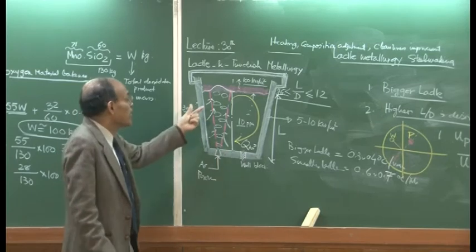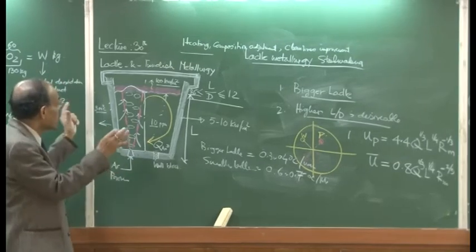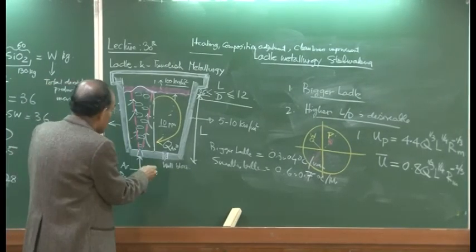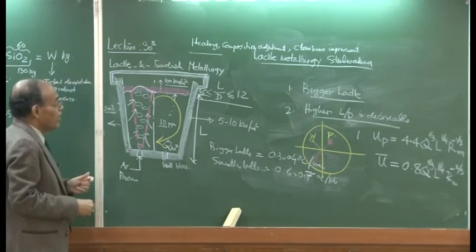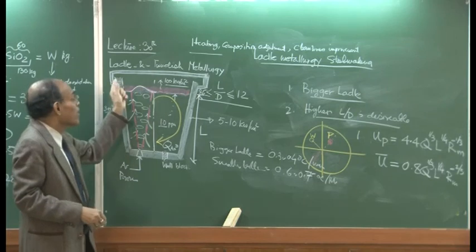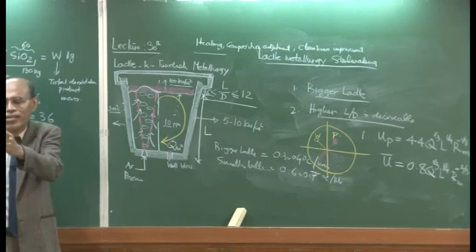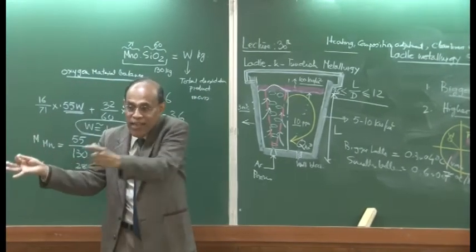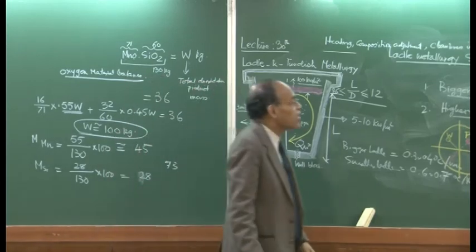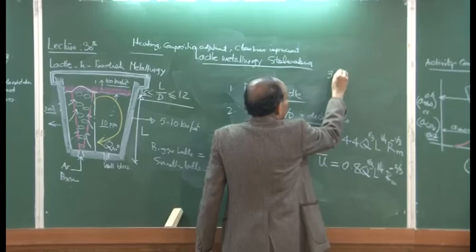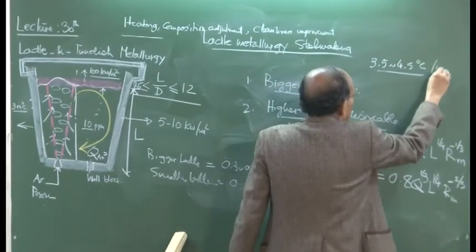So, ladle refining furnaces are used subsequent to tapping operations and deoxidizer additions. The ladle is carried to the LRF station where arc heating will be done. The cover will be removed, and then it is the same sort of structure as the electric arc furnace, with 3 electrodes and a cover that swings back on top of the ladle, and then arcing will start. That arcing will give us heating at the rate of 3.5 to about 4.5 degrees centigrade per minute. That is the rate of heating.